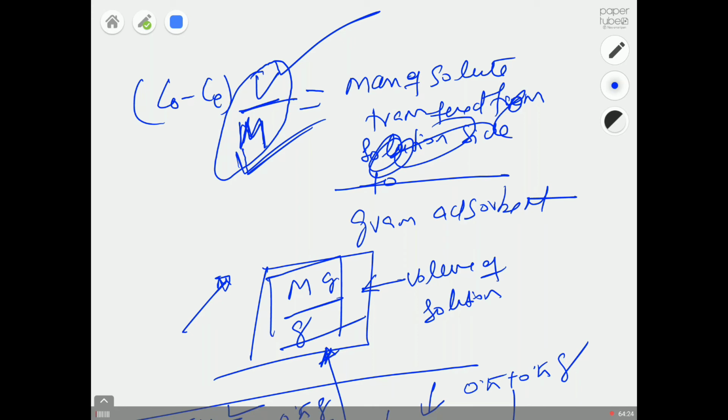So imagine if you do the experiment with some other mass of your adsorbent, we are still getting our normalized value that is independent of the mass or the volume that we use. I hope I didn't confuse you with all these terminologies. The purpose of expressing in terms of milligram per gram is to get a number that I am going to get even if I repeat the same process in an industrial scale reactor.